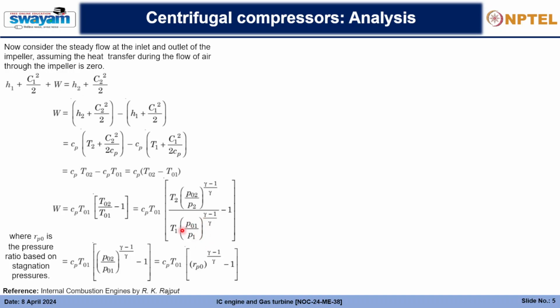And finally, we will cancel out the terms and we will have Cp T01 into P02 by P01 whole to the power gamma minus 1 by gamma, and we will write this as a pressure ratio. So Rp0 is the pressure ratio based on the stagnation pressures. So these are the stagnation pressures, and finally we'll have this. So we have now written the whole Euler's work, or the work done, in terms of pressure ratio.